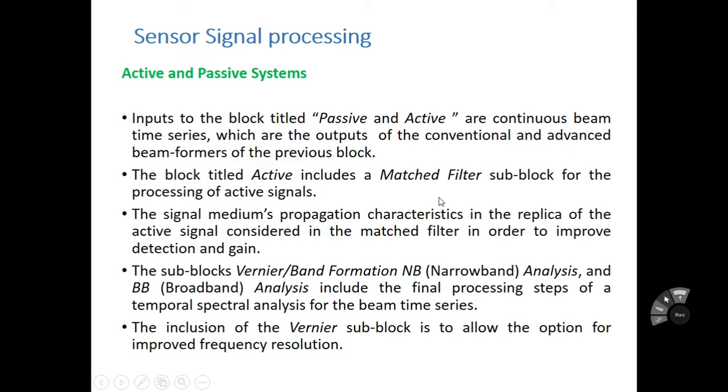In the matched filter, the replica of the active signal is considered in order to improve the detection and the gain, and the subblock of linear or bandwidth formation, narrowband analysis, and broadband analysis include the final processing step of temporal spectral analysis for the beam time series.